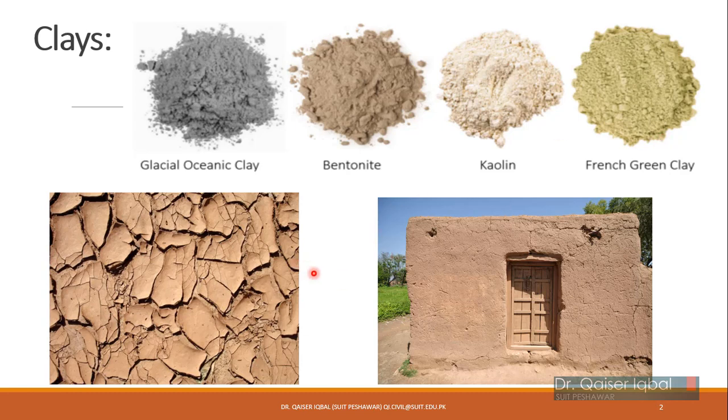So they may be in different colors, and they have various kinds of issues as well. Majority of the time, the issue with clays is that they are susceptible to high volume changes, because they can absorb a lot of water, and when the dry season comes, they can give up a lot of water as well, and then they can form a lot of cracks because of the changes in volume. This is usually not ideal for structures, because if you are putting a foundation in such soil that has volume changes, you can have non-uniform settlements in the building, which is usually harmful.